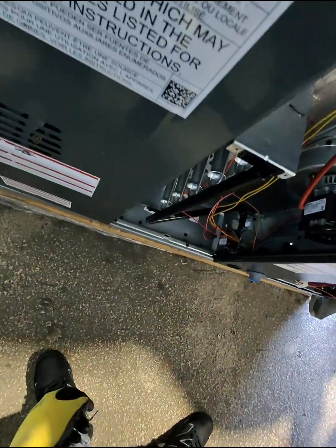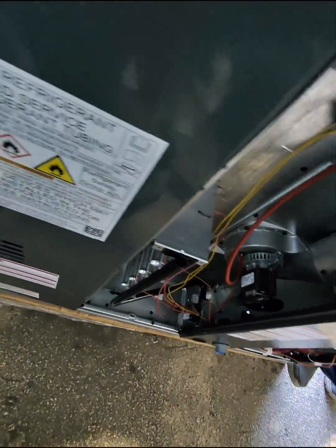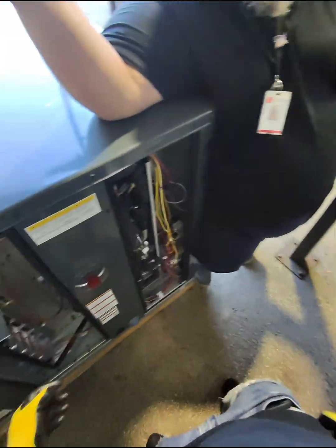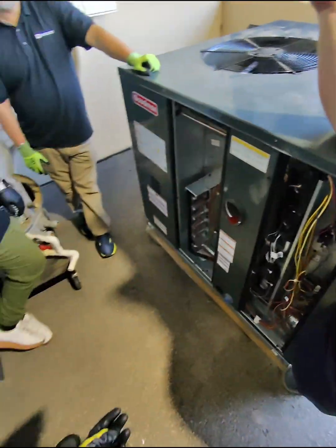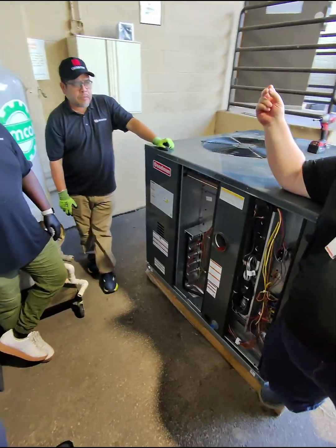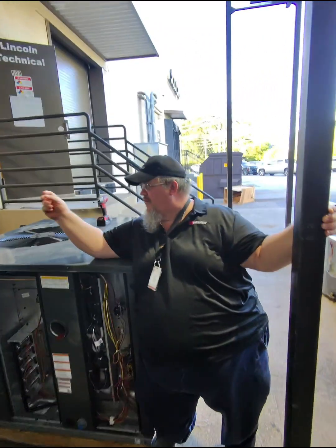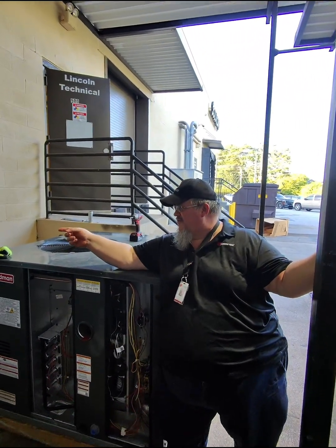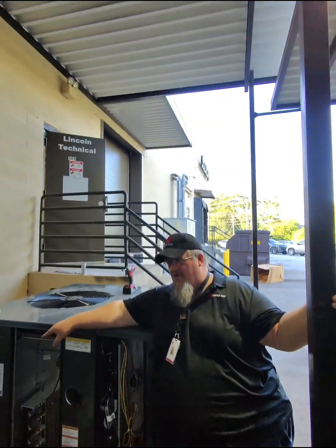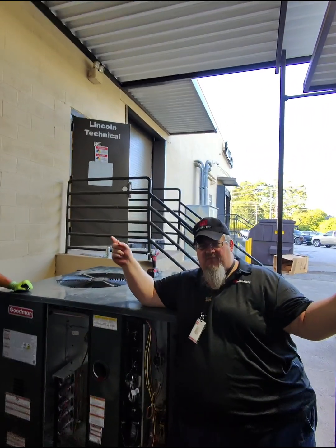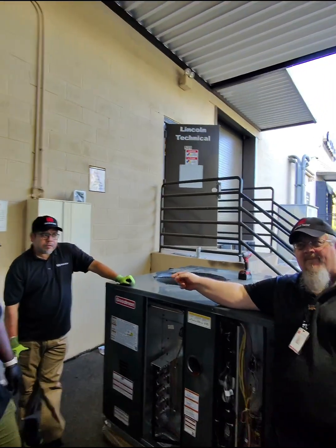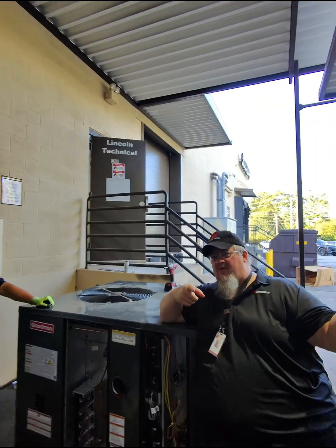Alright, so our gas valve opens up, right? Somewhere down there. So our gas comes on, it hits a hot spark ignition, right? What happens then? Ignites. It ignites, and then it goes across all your burners, hits your flame sensor, right? So our flame sensor senses the temperature. What's it do then? It turns on something. What's it turn on? The blower activates on a time delay.